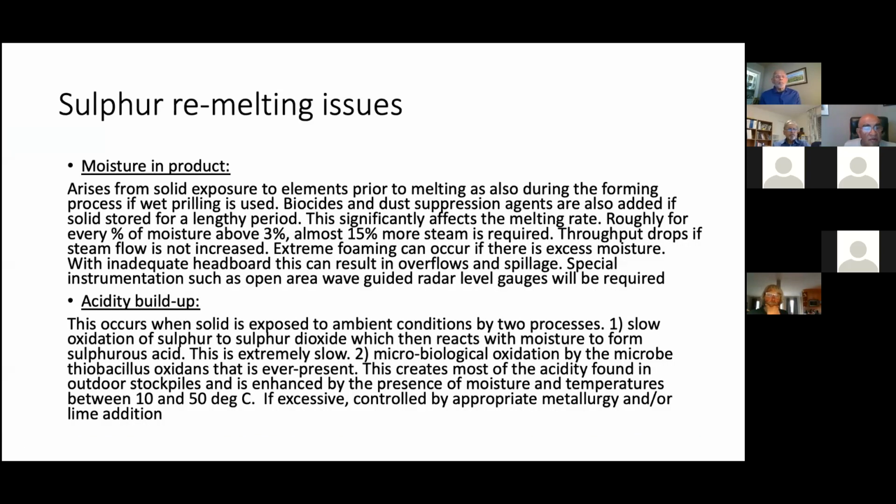Okay, here are the issues that one has to be very careful of. I have experienced pretty much every one of these. Most companies see a block, they see sulfur, and say, oh yes, we can remelt it, let's go for it, and wind up with a lot of issues. First thing, moisture. Now sulfur is hydrophobic, but you can have moisture from rain, snow, things like that. And for example, if you use a wet prilling process where your liquid sulfur droplets are solidified in water, you can have water trapped in there, about 3 to 4% moisture.